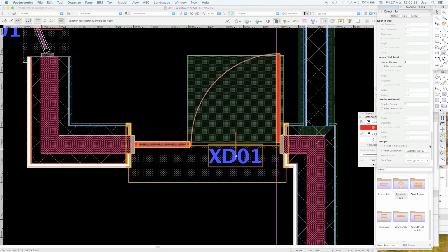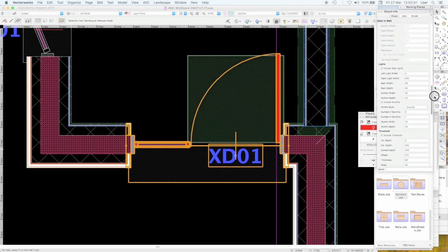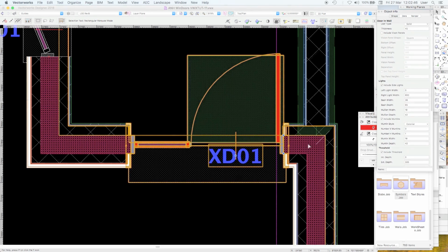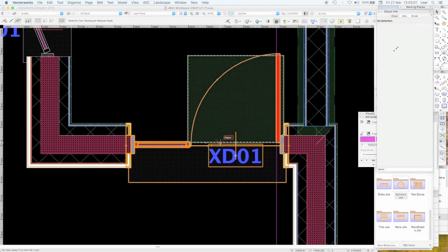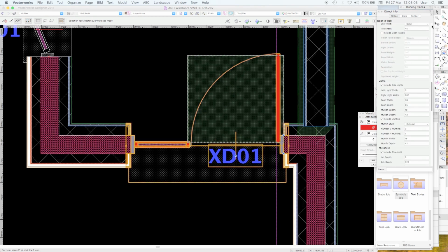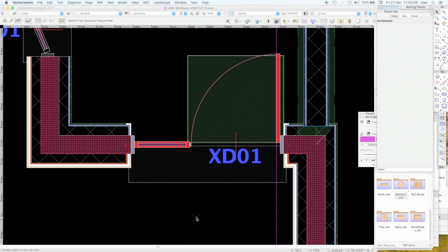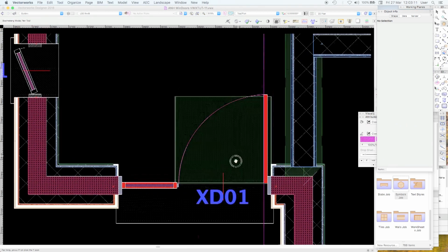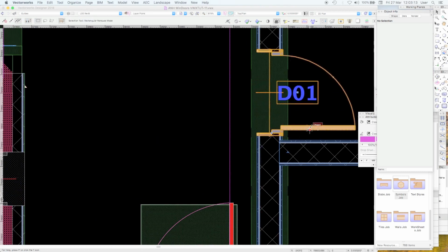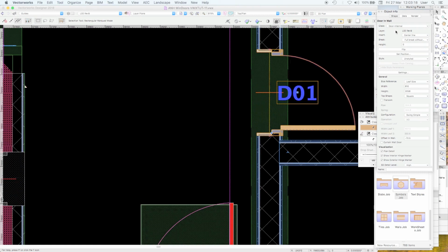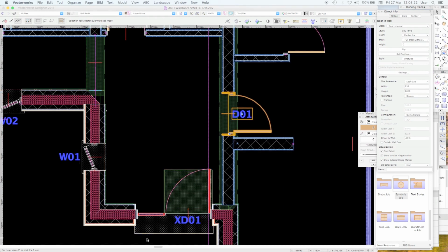But what you notice here, this door has a side light, which is this side panel on the left of the door. The default door class for a door is door main. I prefer to differentiate internal doors, so you'll see that an internal door is in a new class, which I've called door internal. That differentiation I've found useful.